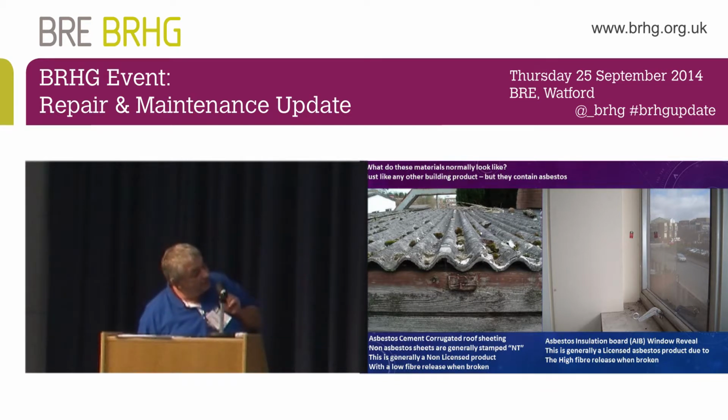Architect and planners didn't do their job properly when they built this, and had to fill in the gap with a bit of asbestos insulation board. Looks just like the concrete until you get it surveyed. It's generally a licensed product.